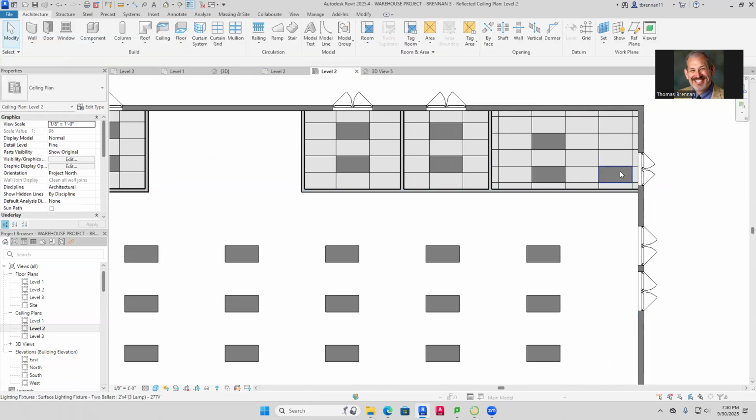Question. You said top constraint of level 3, but for the ceiling, you want it at level 2 with an offset of 12 inches, which is going to be below. Did I write inches? That's 12 feet. Sorry, 12 feet. But actually, it's still going to be below the top of level 3, isn't it? Actually, what's going to happen is level 3 is actually at 12 feet.